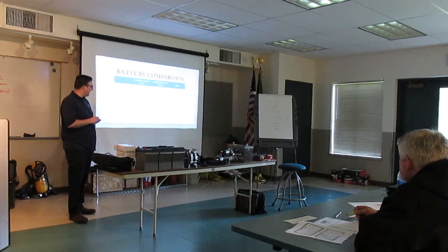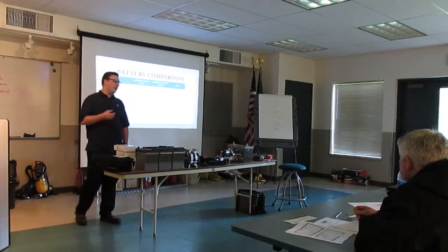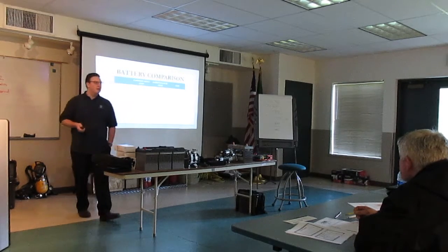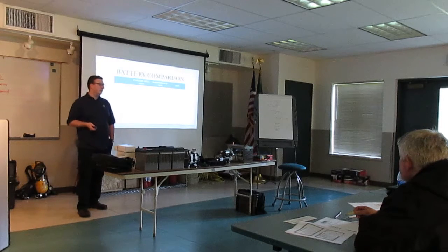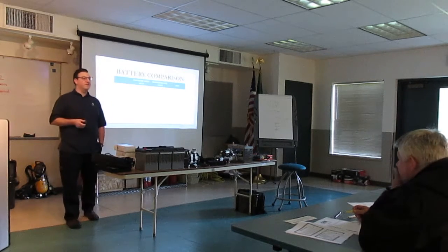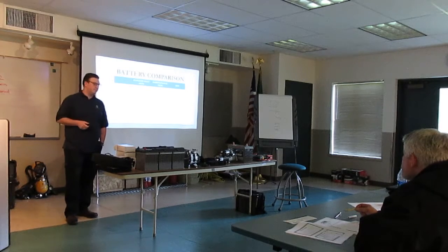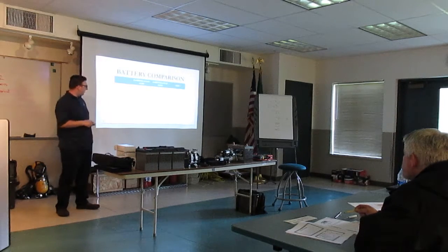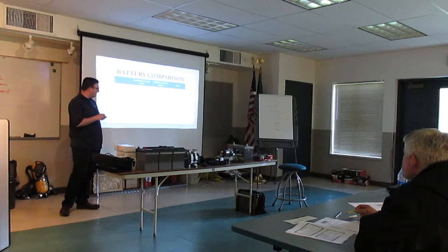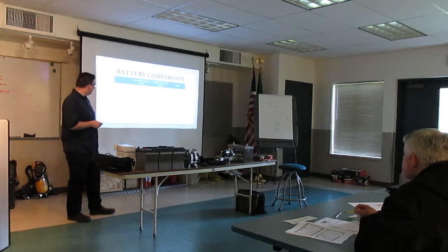When you get to our AGMs, you can have 100 plus. I've seen a transit bus vehicle that when the batteries were depleted down to about 21, 22 volts on a 24 volt system, they pulled over 350 amps when the alternator was able to output enough. So you can have a pretty high pull on those AGM batteries when they're really depleted. You might have to deal with that.